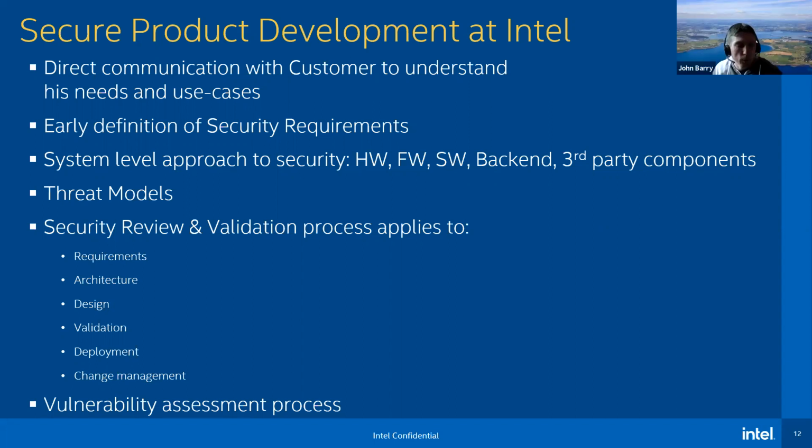Well, it depends though. I suppose it's more for the embedded space, where you've got low level firmware. If there's a vulnerability and a patch is rolled out, it's really important to make sure that an adversary can't roll back to the more vulnerable version of the firmware.